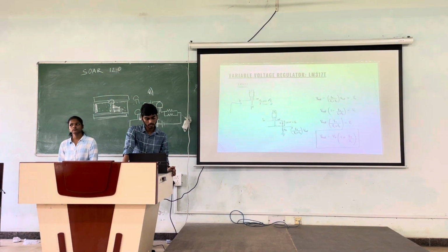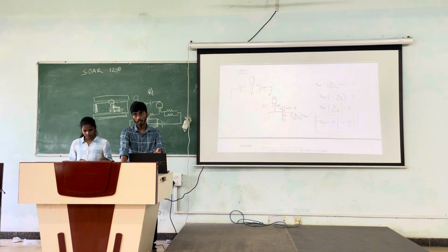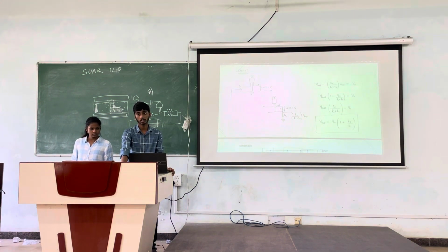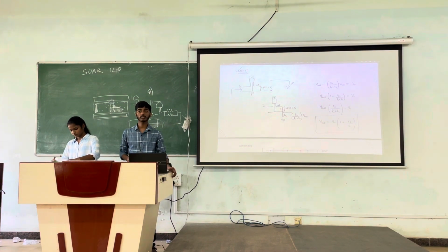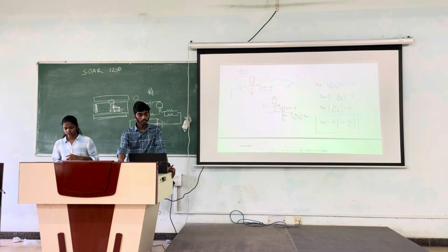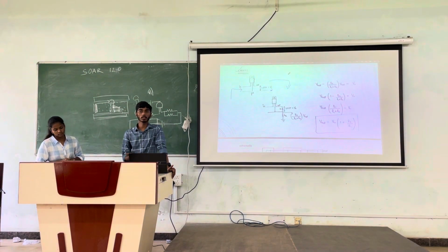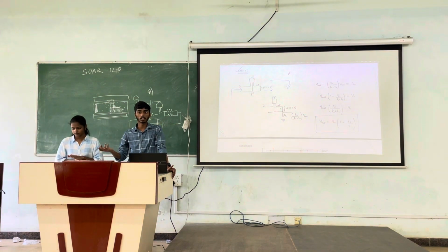So we are using this property of the LM317, that it maintains 1.25 volts at its output terminal, to achieve any sort of voltage which we require. We can have variable voltages, like 5 volts, 7 volts, 9 volts, 12 volts, 13, 14 volts.